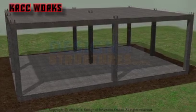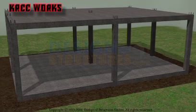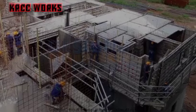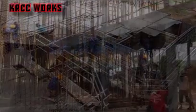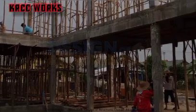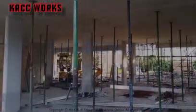Slab shuttering removal. Special attention is required for shuttering removal of flexural members such as beams and slabs, as these members are subjected to self-load as well as live load even during construction. They may deflect if the strength gained is not sufficient to handle the load.